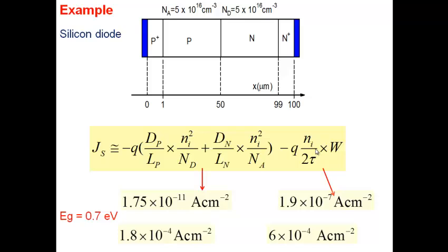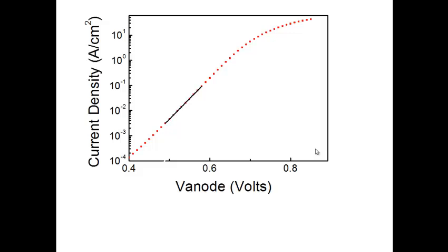Now, this is also a source of difficulty. The difficulty is as follows. Many times, you have done the 380 experiment, where we asked you to measure the current versus voltage characteristics of a PN junction diode. You apply various forward biases, 0.4, 0.5, 0.6, and so on, and you measure current. If you neglect the higher current region, you see a nice exponential, and you fit the exponential and find J equal to, let's say, 3 times 10^-11 exp(qV/kT). So you measure forward current, and you fit it like this, and you obtain this current here.